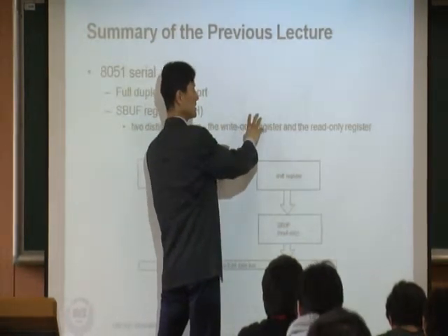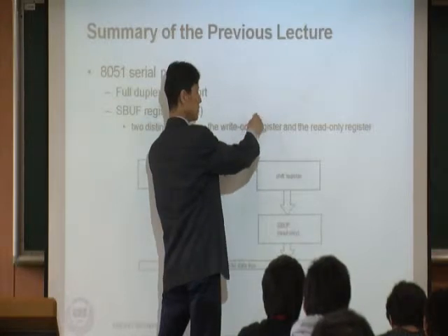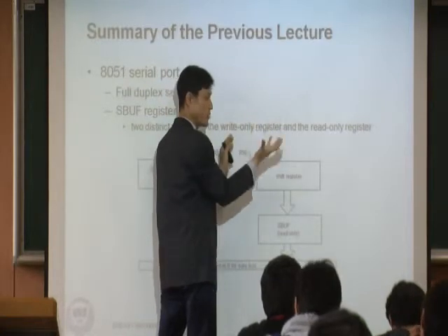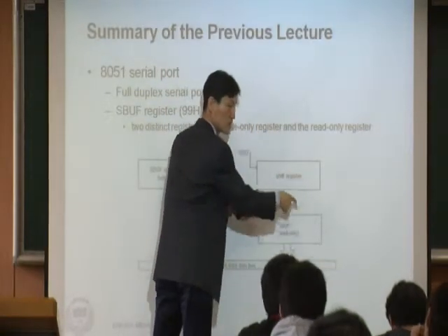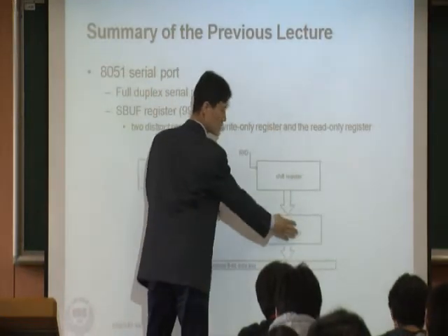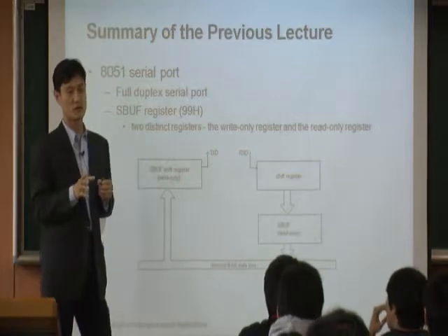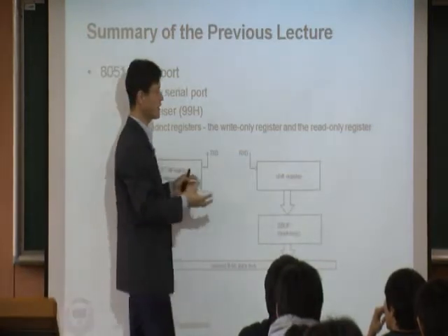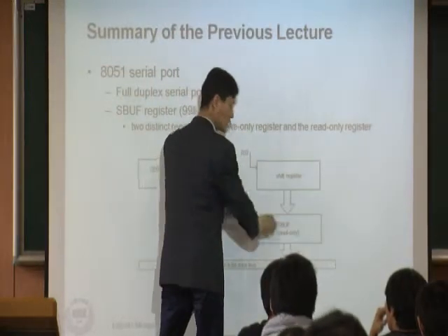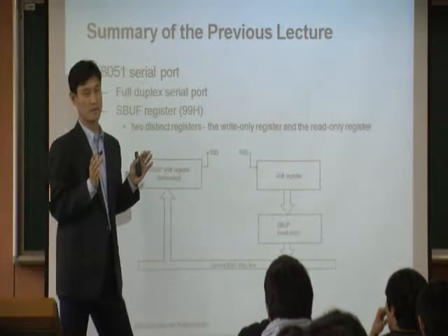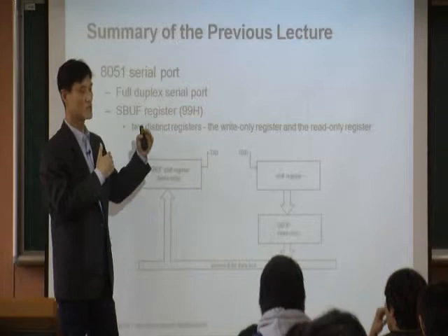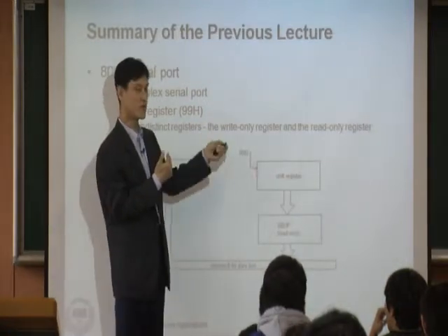You receive that packet, and the hardware converts the packet into the value C. You need to do a conversion from packet to the value C, and put that value into SBUF. That's what hardware has to do. But that kind of process, receiving the packet, recovering C and putting that C into the SBUF, takes time. Hardware cannot do that immediately. Hardware needs a little bit of delay to do all that process.